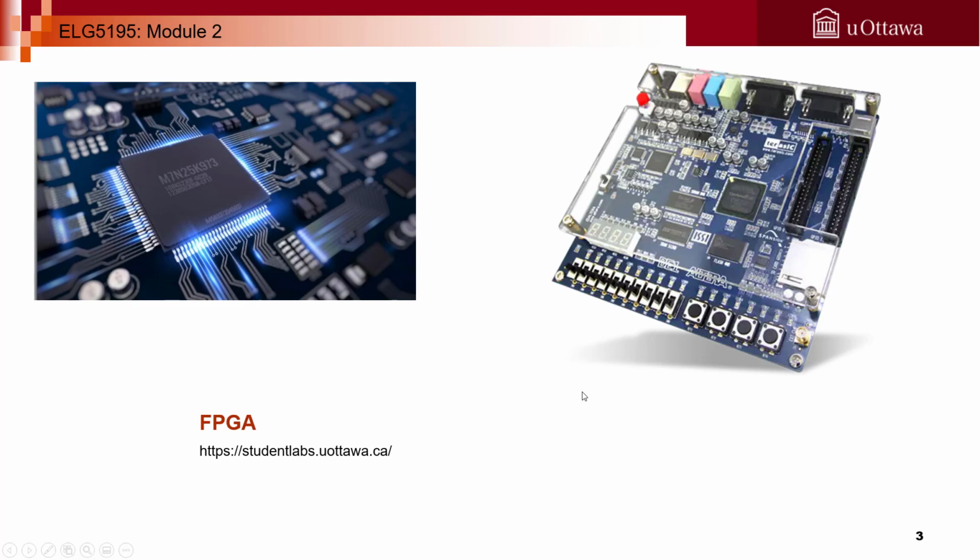What does that mean? You can implement multiple combinational and sequential circuits, and eventually even simple computers using the FPGA. You can upload your design there, verify it, then send it for fabrication. The FPGAs are reprogrammed to the desired application or functionality requirements after manufacturing.